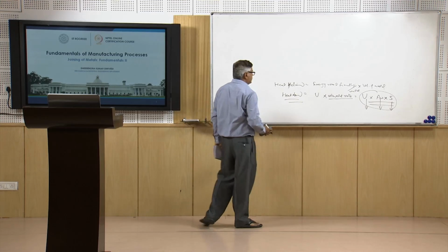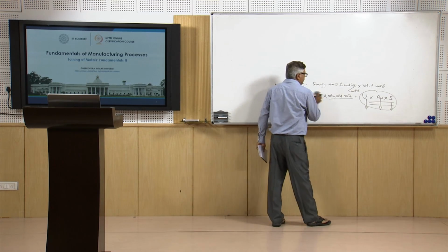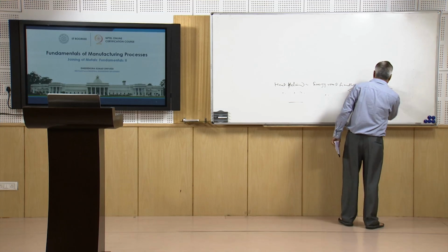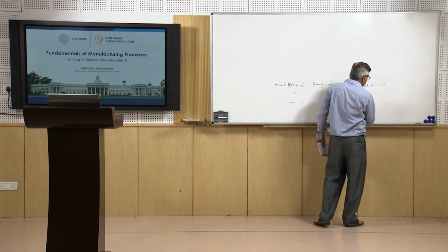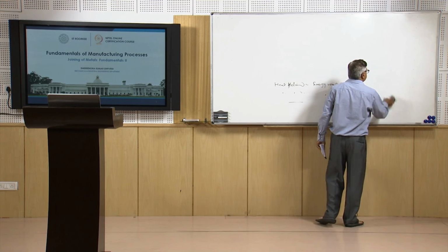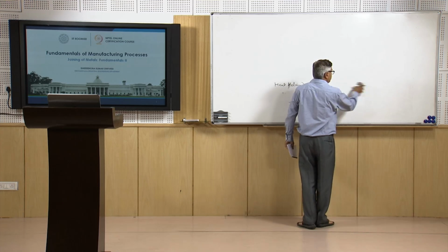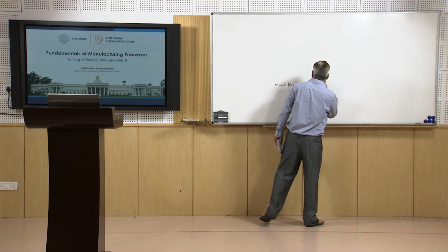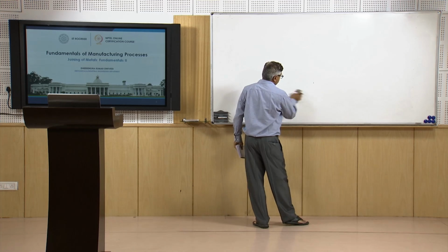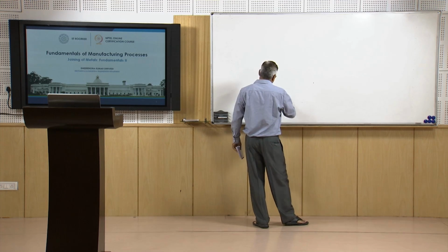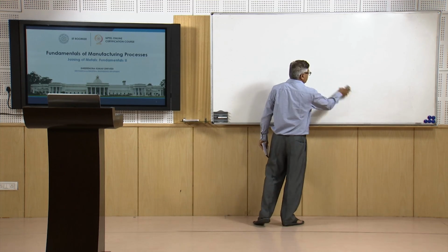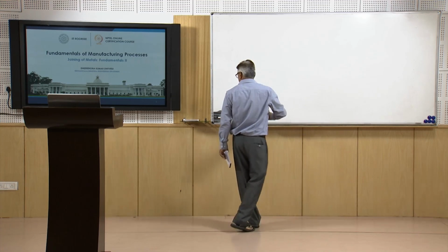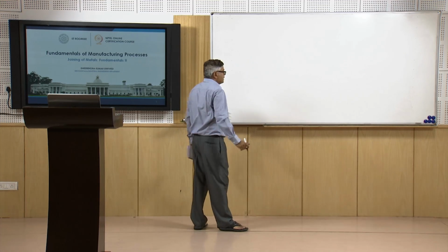This can be used. So, any one that is not known can be determined, like the heat required for melting the unit volume of the material is a kind of property. The welding speed, we will be knowing the speed at which the welding is being done, and from the setting of the welding current, the welding parameters, we can obtain the amount of heat which is being delivered, as well as from the thermal efficiency of the weld.